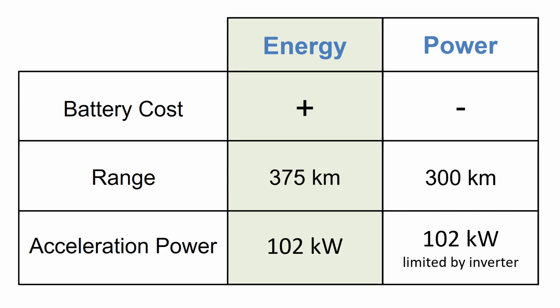All in all, most things speak for the energy optimized battery for this car. The longer driving range might have a high value for the owner, and so does a low cost for the battery. Other advantages of power optimized batteries, like capacity for many charging cycles, have limited value for a normal car. However, for a business application like for a taxi, the possibility of fast charging might be of high value. It's possible, even likely, that a car manufacturer would consider lowering the acceleration requirement such that the battery power may be reduced in order to be able to reduce the battery size and thereby the cost.